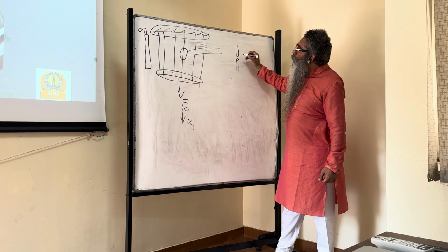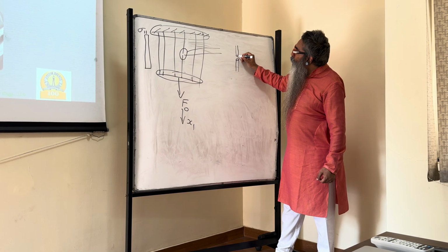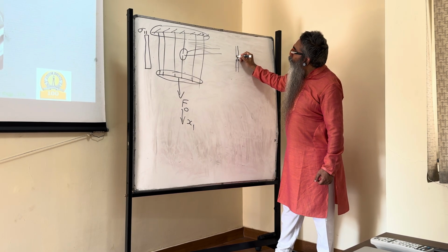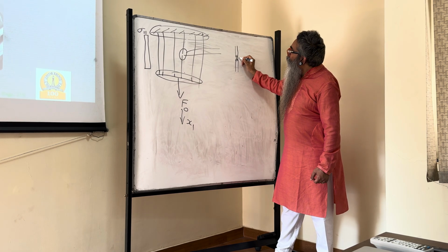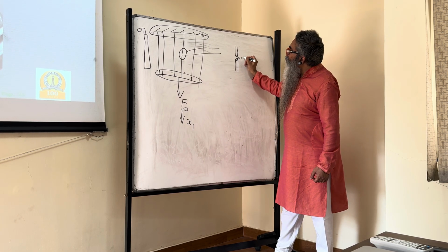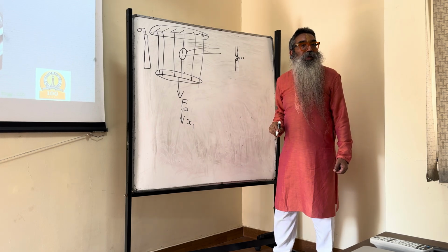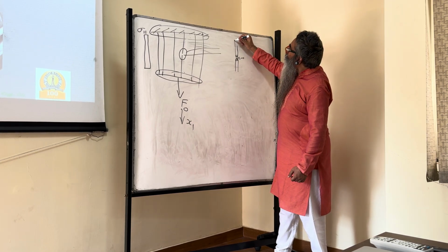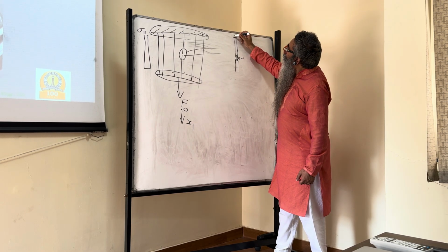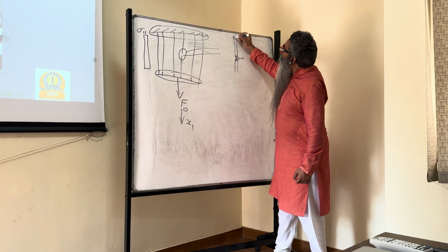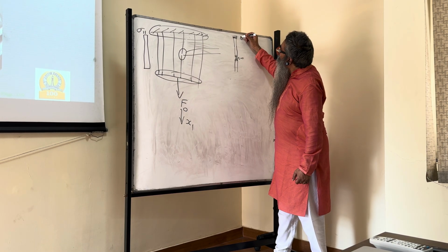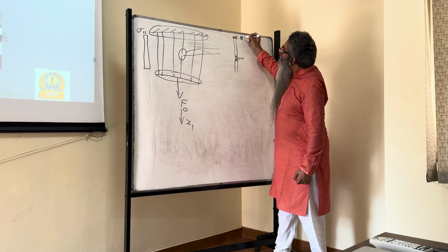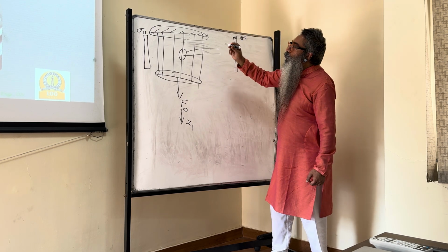Now because it is broken, the stress here, that sigma 1, 1 that we were talking about, and the stress on this sigma 1, 1 is equal to 0. That's the boundary condition that you have there. Whereas where it is attached, if I cut there at that particular location, you would still have that same sigma 1, 1, which was over here.